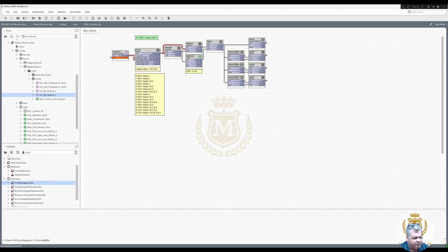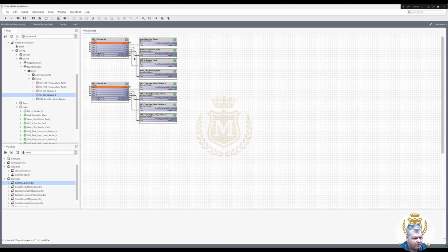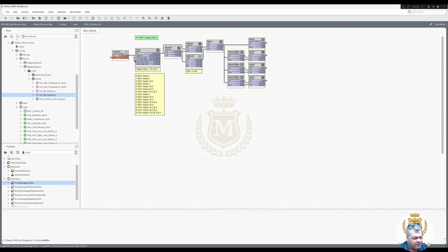So we have a linear reset here. Input low, 0.30, which I've put there, composite it to the out. So you could change it if you wanted to. Same with the input high. So we're going from 0.3 to 10 volts. And then that rescales it from 0 to 15.48, which goes into this modulus block. And there's a 1 there.